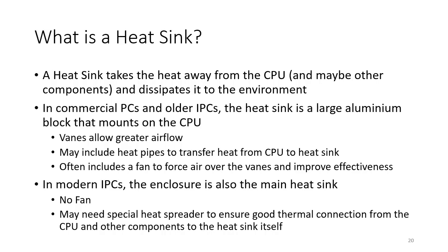Fans have an issue that they're unreliable. A fan might be fine in a commercial environment where you're running 8 hours a day, 5 days a week or 6 days a week or so. But when you're running 24/7, your fans have a problem that they will wear out. And even a really well-engineered fan might seize up after anything from 3 to 5 years, which is less than the expected life of our industrial PC. So even the most reliable fans probably aren't reliable enough for an industrial PC, and you'd need to think about some sort of maintenance if there was a fan installed.